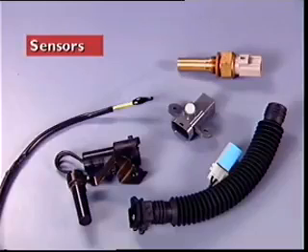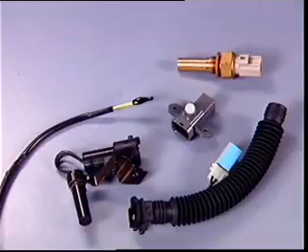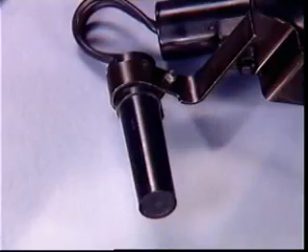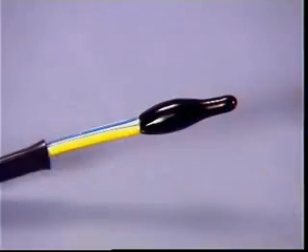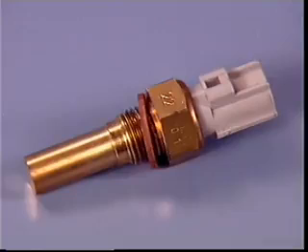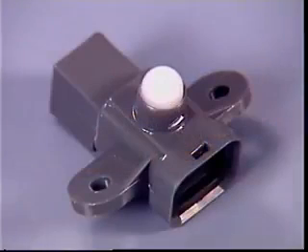This section examines sensors for automatic climate control air conditioning systems. The electronic control unit needs to know the temperature of the outside air, the cabin air temperature, the temperature of the air conditioning evaporator, the temperature of the coolant circulating through the heater core, and if the vehicle is in bright sunlight.